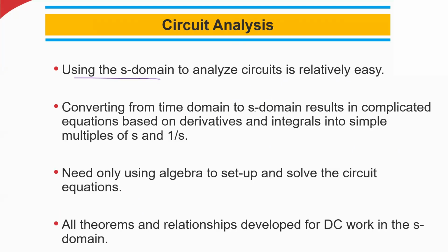Converting from time domain into S domain turns complicated equations based on derivatives and integrals into simple multiples of S and 1 divided by S. If you use the simple mathematics in the time domain, the equations will be more complicated and longer to solve. That's why we are using these Laplace transforms.